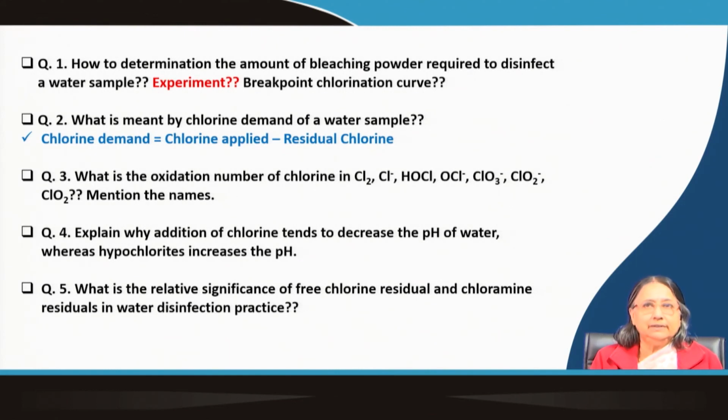What is the relative significance of free chlorine residual and chloramine residual in water disinfection practice? I told you that during transport the combined chlorine residual is very important, isn't it? That is the chloramine residual. And free chlorine residual, although it is a better disinfectant, is dissipated fast.